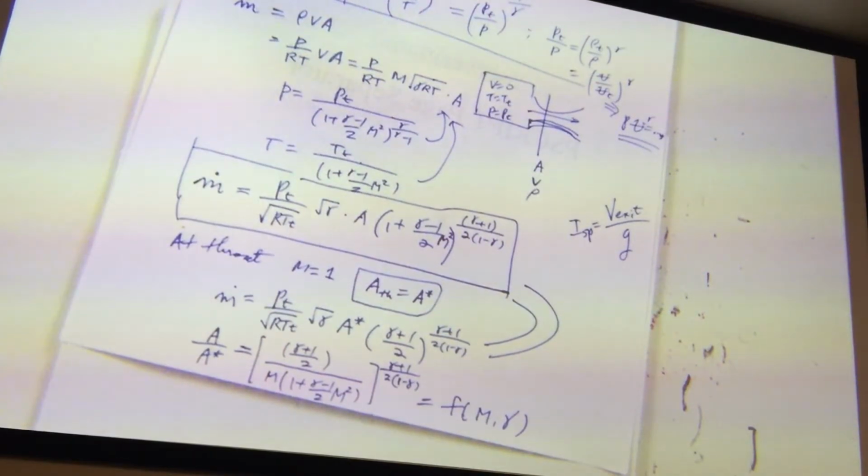So, if you want to jump ahead and check out the propulsion book, especially the rocket chapter, then you will look at the typical specific impulse of chemical rockets, right? Solid rockets probably give you 300 something, liquid rockets probably give you 200 something seconds. Specific impulse has the unit of time. And when they show me this little rocket, they buy it. Oh, specific impulse is in the range of 200 or 300 seconds. And that's like a real big rocket, it's the same thing.